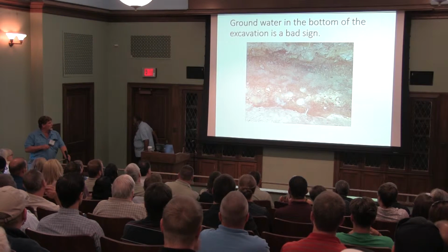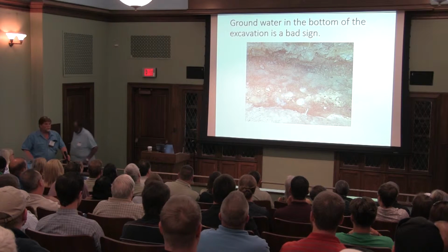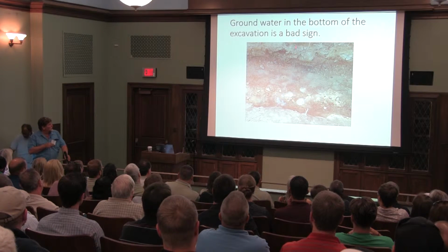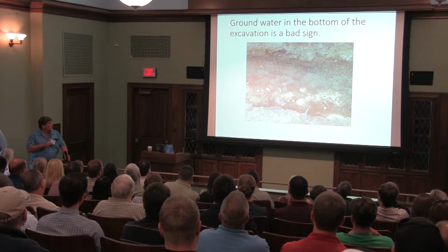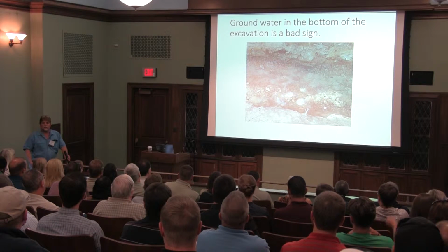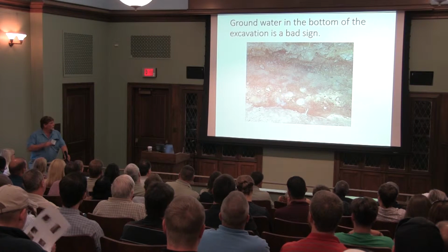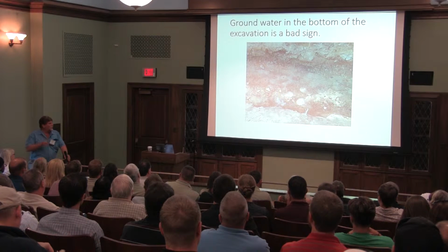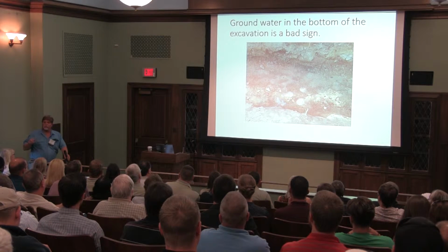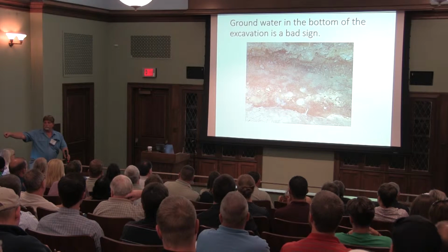This is another attentive grading area. We actually hit groundwater. That trench, that's grass. That trench is only 2 feet deep. Then when we were excavating, we hit groundwater. So, fortunately, this also had an underdrain, but people talk about failures. Some of these failures need to be addressed front end.